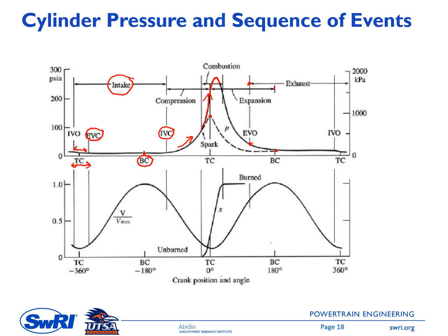It means this pressure is only due to the compression process. And you can see in this feature, the difference of this area is due to the combustion process. This is the work that is generated by the combustion process and then transferred to the piston.